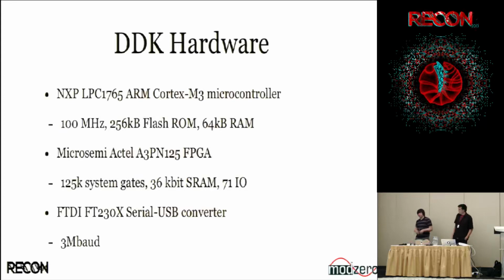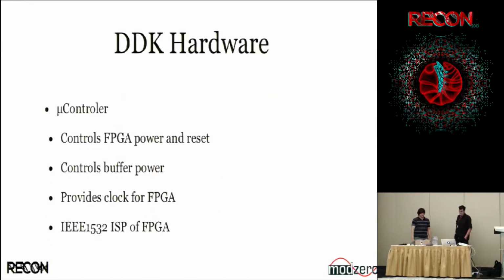But as opposed to all the others, although I'm going to go out on a limb and guess that the MSP430 is not a 32-bit microcontroller, but I never actually played around with them, these are full-blown 32-bit ARMs. That means in one memory access, you get 32 bits back. This can also be very useful if you're trying to speed things up. So it's a better choice in general.